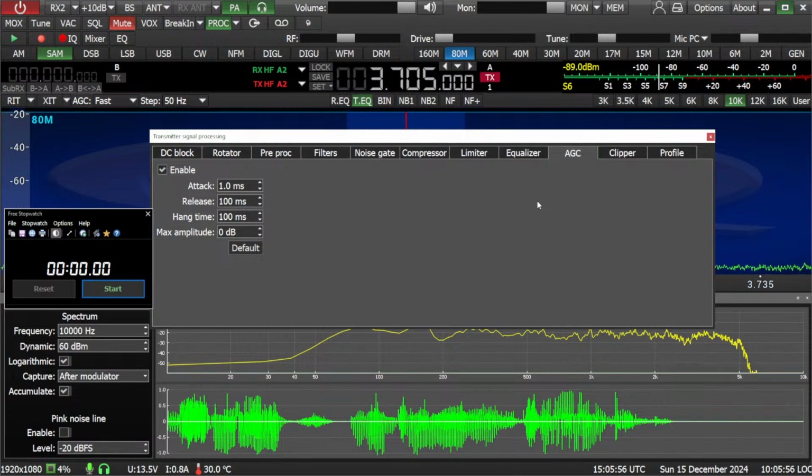Well, come to find out, someone told me that I had what I call a reverse swing. Under modulation, he was watching my carrier level drop. That's not supposed to happen. I quickly realized, and this is something to watch for on your power meter, that if you set your power meter to average, your output watt meter, as you're modulating, you shouldn't see that carrier level drop under modulation. I looked at my power meter, and sure enough, it was dropping. That's not supposed to happen.